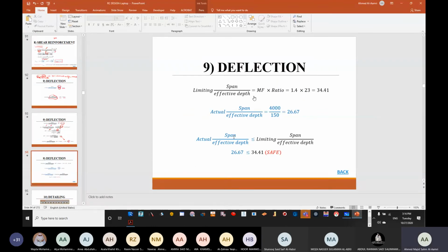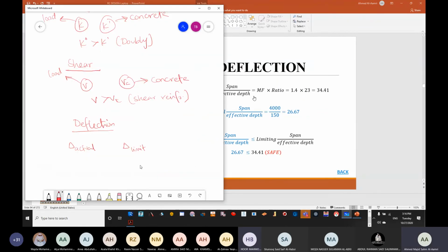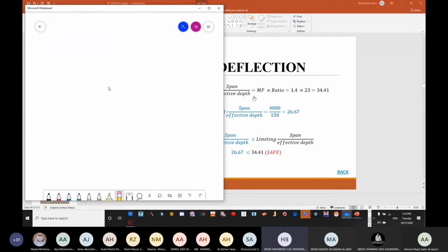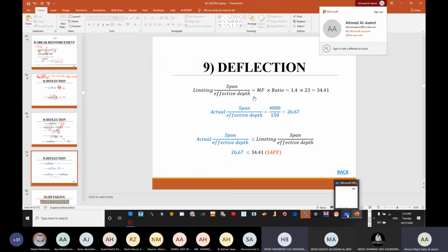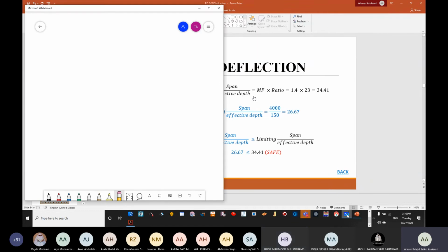Sir, the effective depth which you use, which is dx, it corresponds to the higher shear, which was in the equation of the highest dx. So corresponding to that, we use dx. No, for deflection we choose the higher between dx and dy. See, the highest deflection will be caused by which moment? The highest deflection will be caused by the biggest moment, right?